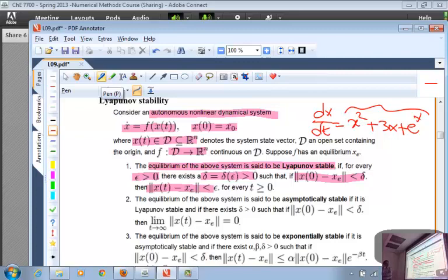Let's try to put a figure in terms of the state space that we talked about. So this is a two-dimensional system. Let's say this is x1, x2. There are two state variables. And xe is the equilibrium point of that particular equation. That is, if I set f of x equal to 0 and solve for that, I get some point. I will have a solution for x1 and x2 that satisfies that algebraic equation equal to 0. So I'm going to call that xe. So we have kind of figured out what xe is.